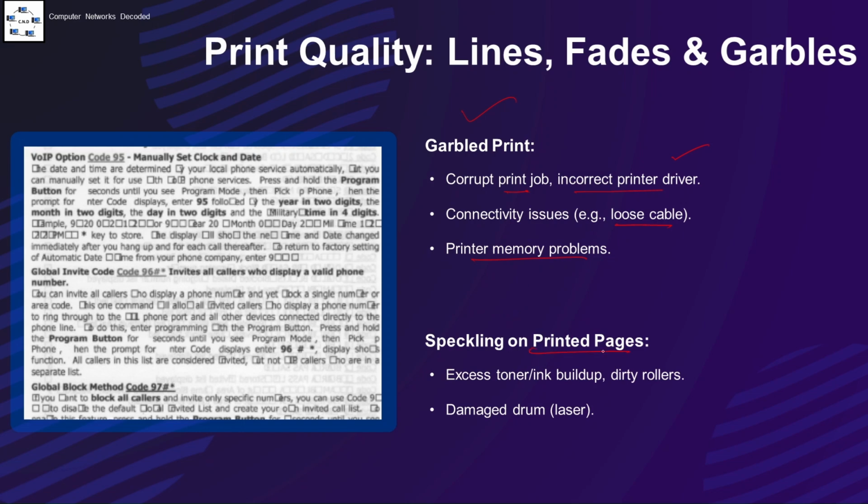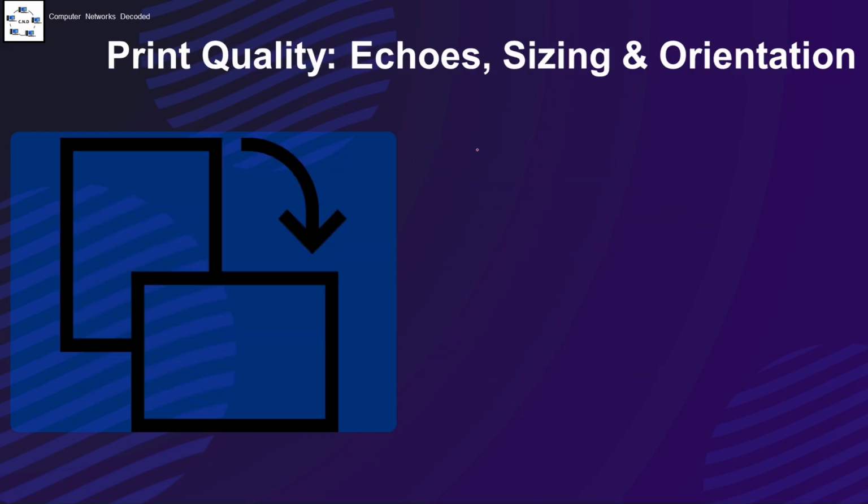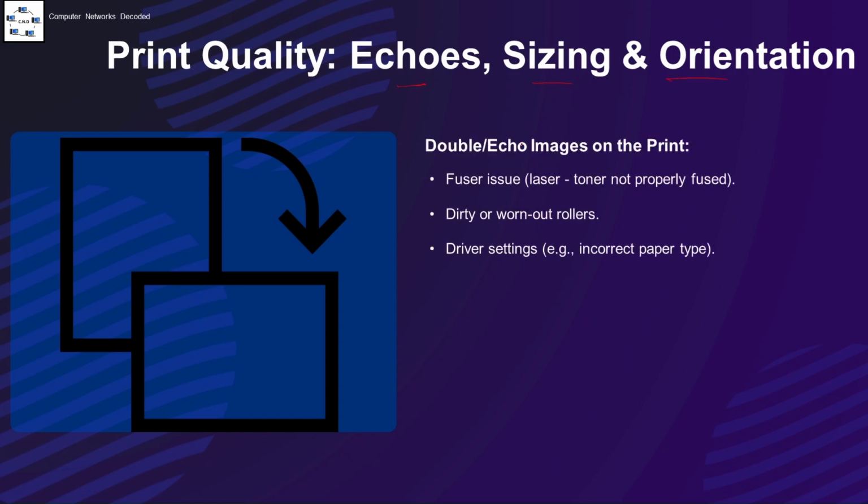Speckling on printed pages: excess toner, ink buildup, dirty rollers, or a damaged drum in laser printers. Print quality issues such as echoes, sizing, and orientation.